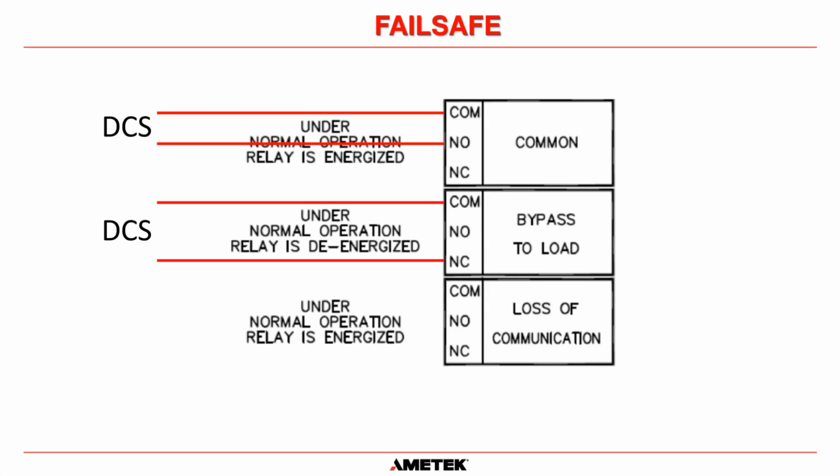And then when the UPS gets to the plant and the DCS engineer is involved, he turns around and says, well, I've only got enough room to accept 1 alarm from your UPS system. All the other terminals are full for our DCS system.